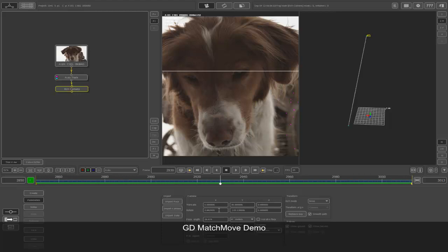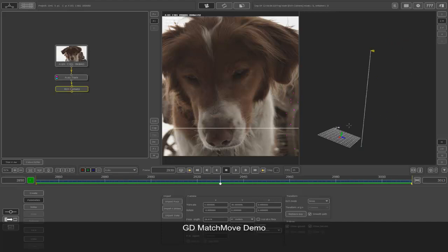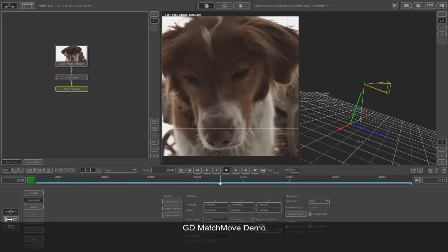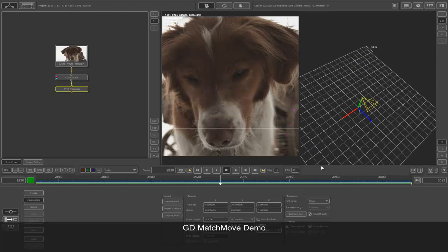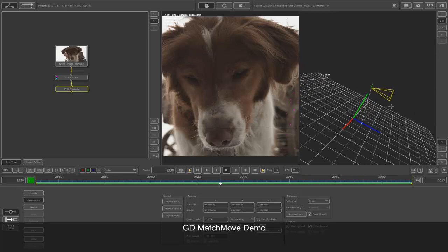So I'm going to zero out all the values. We also need tilt on the camera, so I'm going to set the tilt angle, and the tilt angle we saw was 8 degrees. I'll go to the x-axis and put in -8, because that is what is going to tilt my camera 8 degrees up. If I zoom in, you can see that my camera is tilted up 8 degrees, and it is set properly in the center of the grid. And that is almost done.